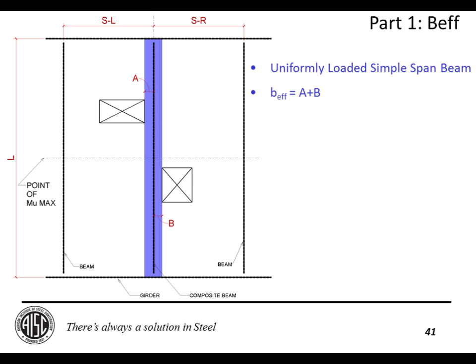But there comes a point in time in which perhaps that beam was already fabricated, it's already erected, and the HVAC guy just figured out what size unit they're going to put, and they need to put some giant openings right next to your beam that you weren't aware of. So you might need to sharpen your pencil a little bit and see if you can get some more out of that slab. So in that same paper, Mr. Weisner